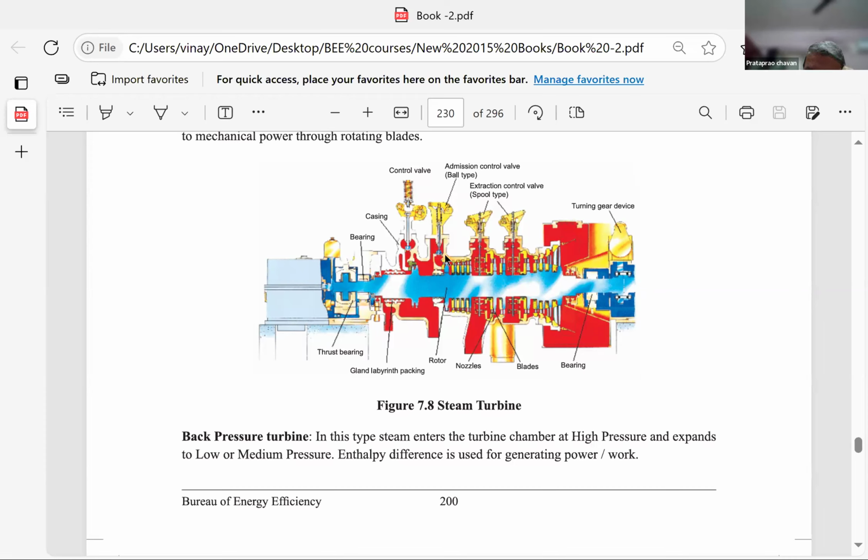Not here, but here, because the process requires 100 kg steam. Suppose it requires 125, I will tap it here, between 150 and 100. So one turbine can be extracted or tapped at different pressure points and temperature points, so that it has a wide variety of applications. A plant requiring 3 or 4 parameters of steam can have it.